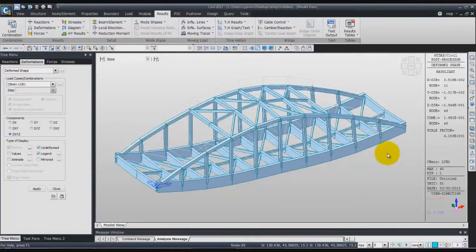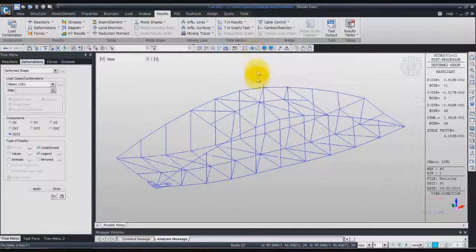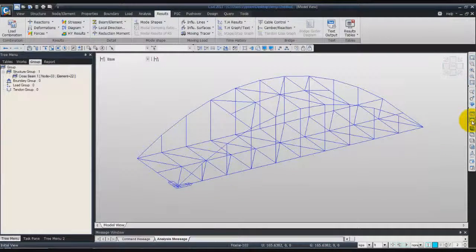Now let's look at the shear force and the beam diagram. So hide again the section and come back to the initial view by clicking here on initial view. Now we'll select only this face in order to see the beam diagram in this section only.